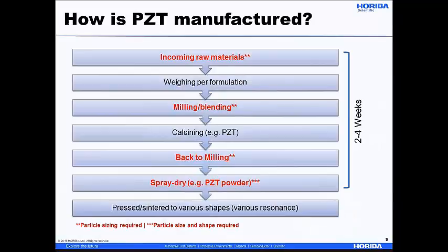Okay, so how is this piezo crystal manufactured? This is a typical workflow here. You have incoming raw materials, and when you get the first incoming raw materials, you definitely want to monitor your particle size, then you weigh per formulation, and you start milling and blending.